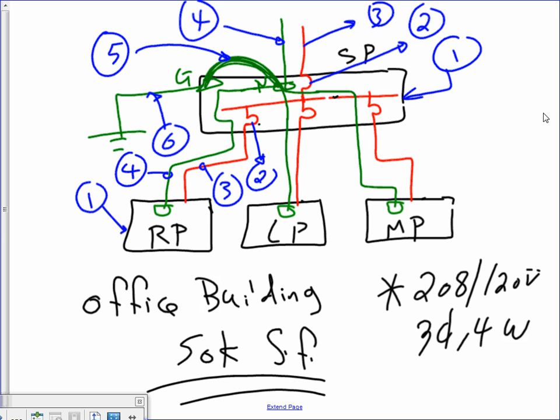Here's what we have. We have the electrical utility. The red is the power line. We're coming from Xcel Energy, bringing power into a panel that we're calling SP, service panel, exactly like you guys are doing. From that service panel, we're taking chunks of power. That's what the riser is. They chunk the power. One chunk is to feed a panel that's called the receptacle panel. Does that sound familiar, Derek? Is that what we do for a commercial project?